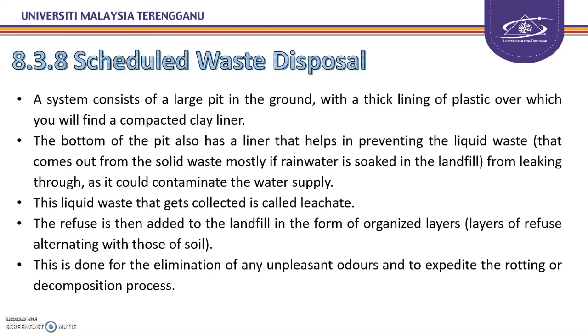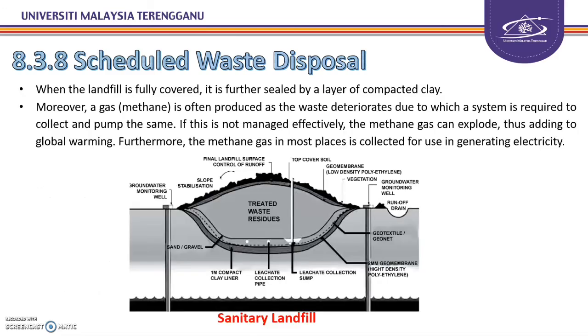The refuse is then added to the landfill in the form of organized layers. They will add the waste layer by layer, and after that they will fill up with soil to prevent any reaction of this scheduled waste. This is also done for the elimination of any unpleasant odor, and to expedite the rotting or decomposition process. So you can see this is the sanitary landfill, a complete system.